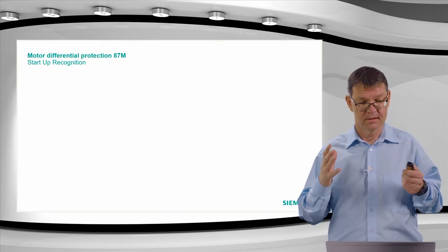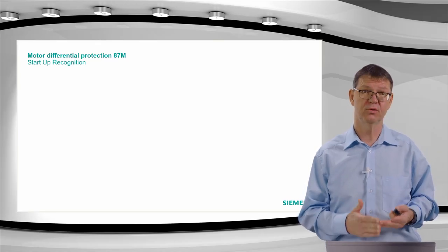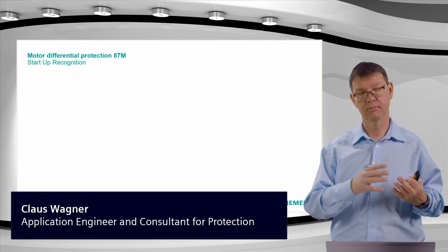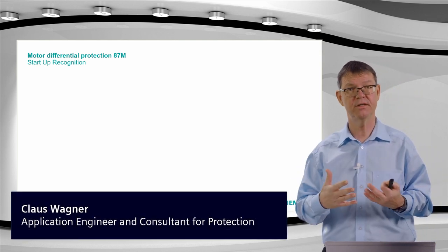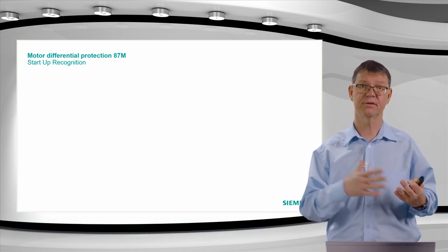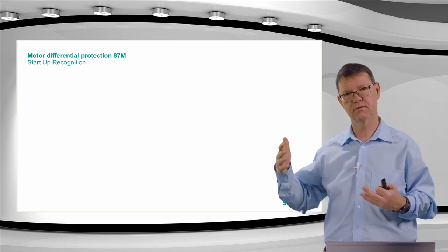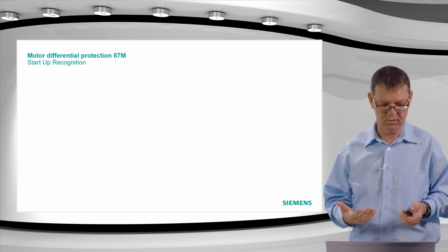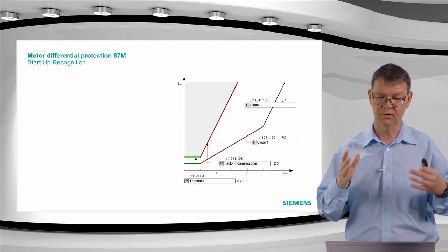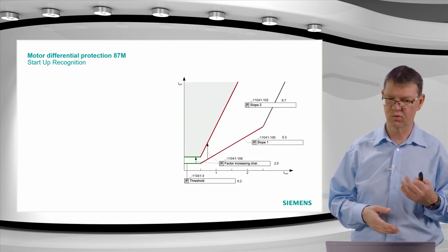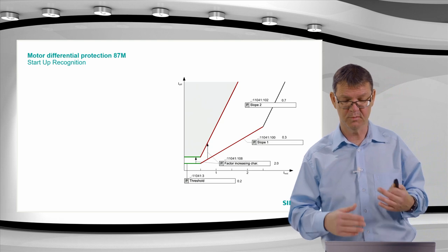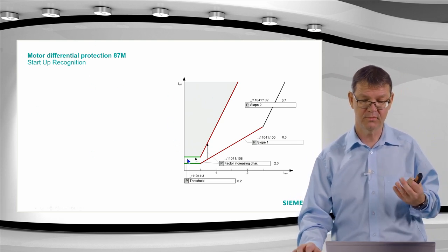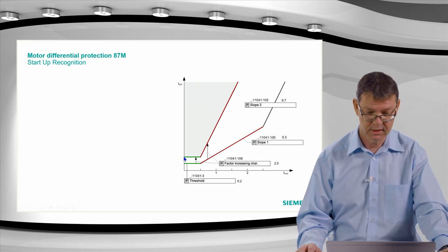Good. Startup recognition is a special function only for the motors, because there we have to deal with a long time of elevated currents during the startup. I said this can take seconds, 10 seconds, 20 seconds, and this could also stress current transformers. And we found here and there problems with the current transformers. So therefore we have the possibility of this startup recognition and to react when we see there's a startup of the motor.